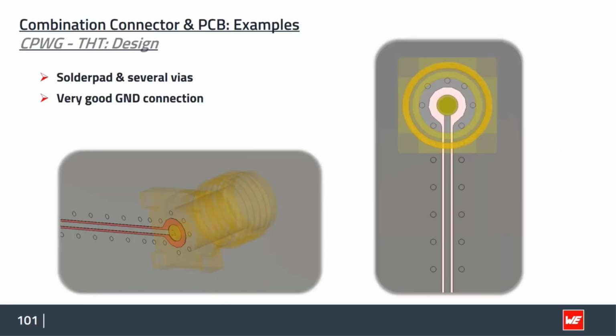So at first we put this part on top of the PCB, of course, and we have the via fence running throughout it. As it's a circular system, the via fence is of course going around, and we are doing a circular ground taper in this case to compensate the parasitics. And as this pin sitting on top here is quite massive, it's also necessary to add an additional DGS structure to fully compensate the capacitive parasitics.